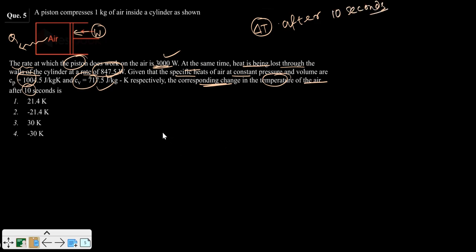Okay, so again we have to apply the first law of thermodynamics over here for the process when the state properties are changing from state point 1 to state 2, right? So del Q will be equal to again du plus del W, but all these terms should be written in the form of rate. That means we can say del Q dot equals du dot plus del W dot, right?